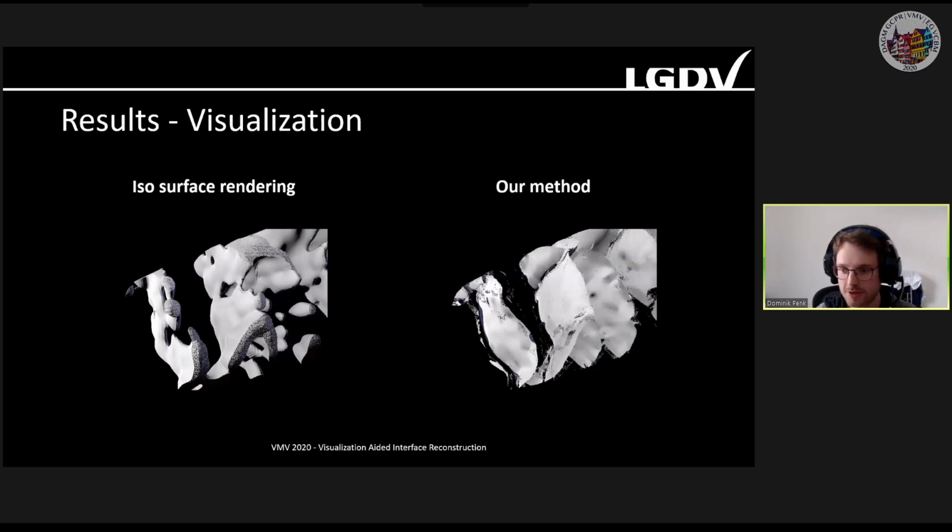Okay, so I also brought some examples of the result here. On the left-hand side, there's our first approach, because we thought, okay, we are visualizing a volume, so let's just do iso-value rendering or iso-surface extraction and then rendering. But there are some problems here. For once, we don't get these nice 2D surface structures because by design, iso-surfaces are always watertight meshes, so we generate a hull around the surfaces. And as I also already said, the density along the surface might change, and therefore you cannot find a single density value which generates the entire surface, and you get very many holes.